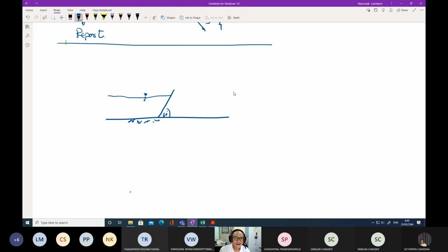If we reduce the opening area, the velocities will increase. The increase of velocities will finally increase the loss, and this loss will create the water level difference between the front and behind the screen.